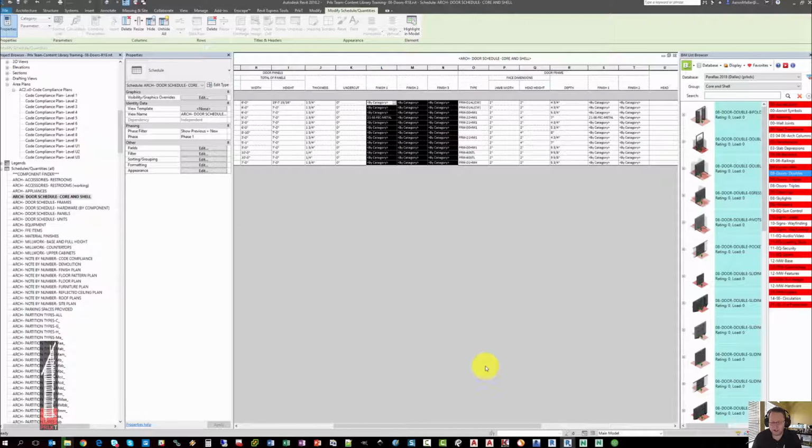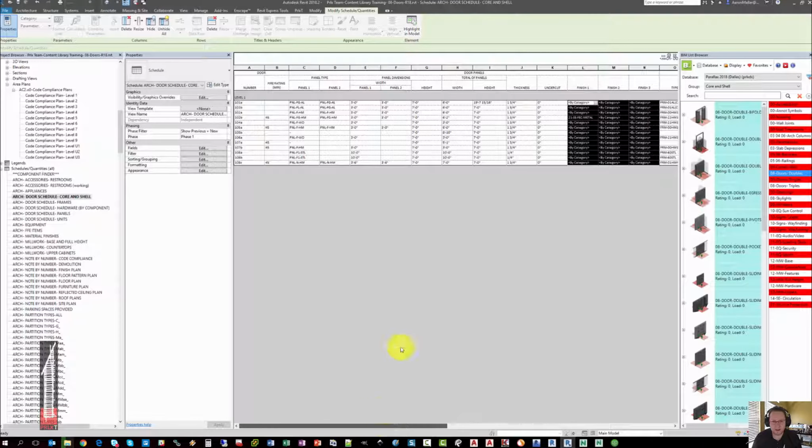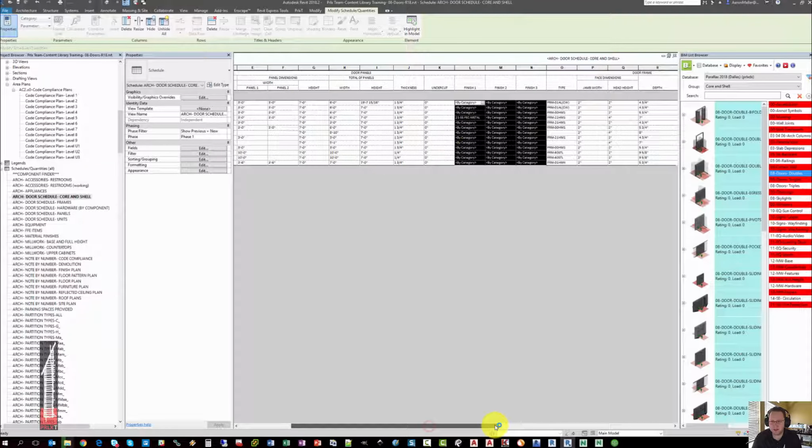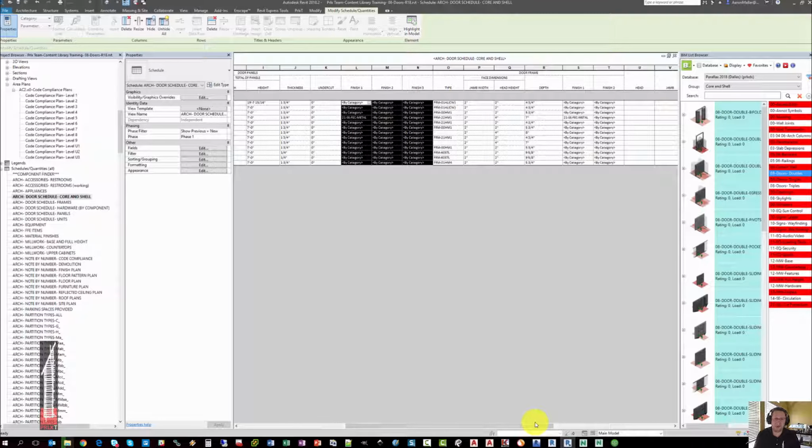You'll notice that there is not a set of parameters for door construction material, and that's because the frame selection is already covering whether or not it's an aluminum or a wood or a hollow metal door. This allows us to not have to use redundant text parameters that we fill in the 11th hour, which means better quality control of our process earlier on.